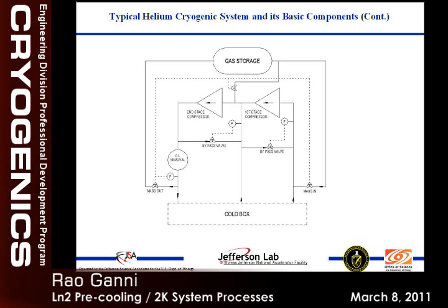These are able to, because the enthalpy is the same. If we put in 6 megawatts, they would melt and you would have iron flowing down. But we are only using the availability created by the 6 megawatts. That's what these are basically wasting. It's not the total energy. Otherwise, like I said, all these pipes would be molten iron on the floor.